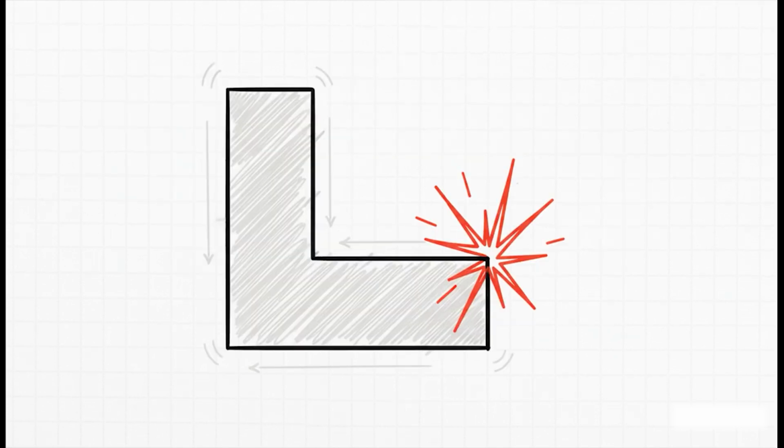And finally, re-entrant corners. This is for any building that isn't a simple box. You know, your L-shapes, T-shapes, U-shapes. When an earthquake hits, the 2 wings of an L-shaped building actually try to vibrate on their own, moving in different directions at different times. This creates an unbelievable concentration of stress right there in that inside corner, stress that can literally tear the building apart.